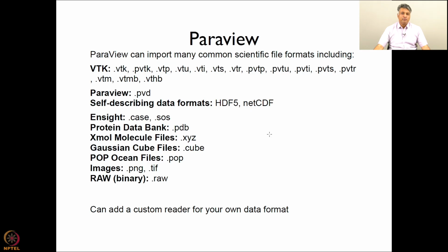ParaView also can import many common scientific file types. The thing is, you could be using some commercial software, or you could be using some other proprietary format or other open source formats. So for example, it will take all the VTK file extensions, which are exhaustively listed here. It will take the ParaView specific extension .pvd. You have other self-describing data formats, which are popular with high performance computing, which is HDF5 and NetCDF.